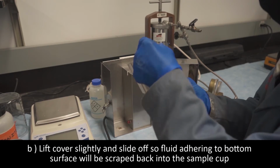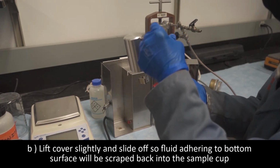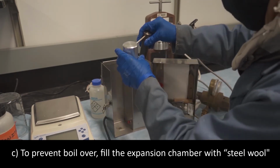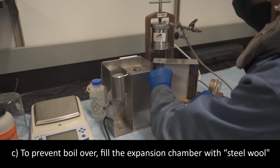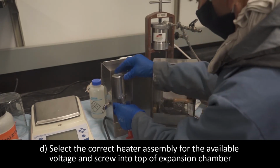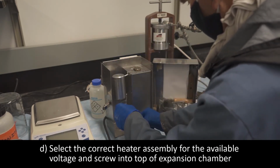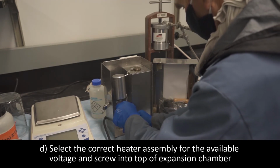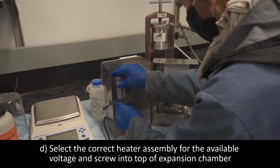B. Lift the cover slightly and slide off so that fluid adhering to the bottom surface will be scraped back into the sample cup. C. To prevent boil over, fill the expansion chamber with steel wool. D. Select the correct heater assembly for the available voltage and screw into top of expansion chamber. Keep assembly upright so that mud does not slosh into the drain tube.